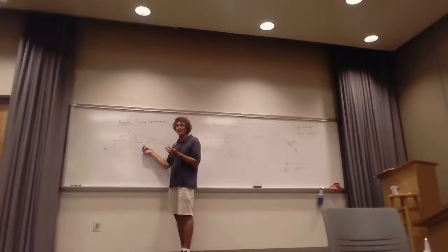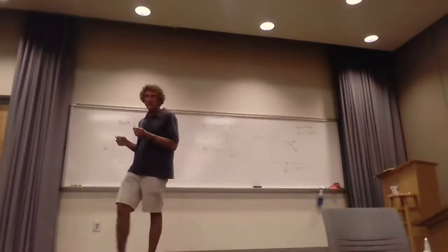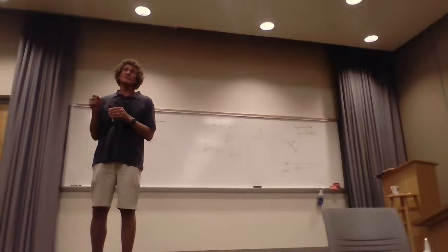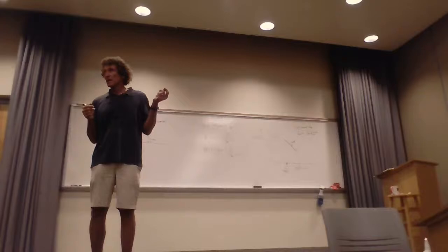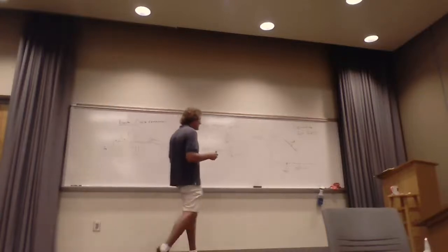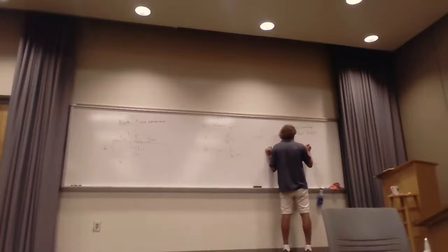When I look at this, you've had resonance phenomena before, right? In your circuits courses, remember the resonant frequency was always 1 over 2 pi square root of LC for any kind of L and C in parallel. Do you all remember that? Or series, correct, class? It is here too. When you plot these things out with MATLAB, you'll see it. It'll come down and hit a relative minimum here, and then it will start going up after that point at 20 dB per decade.